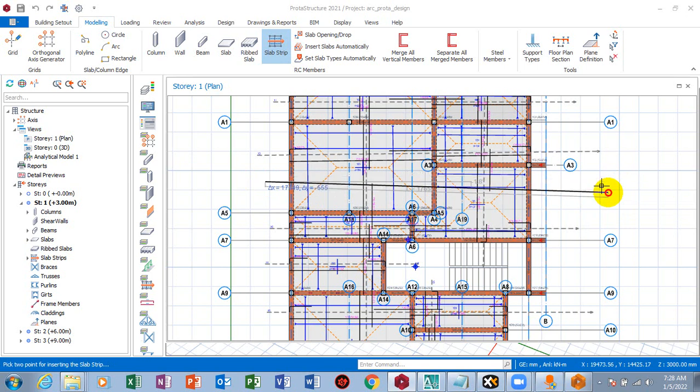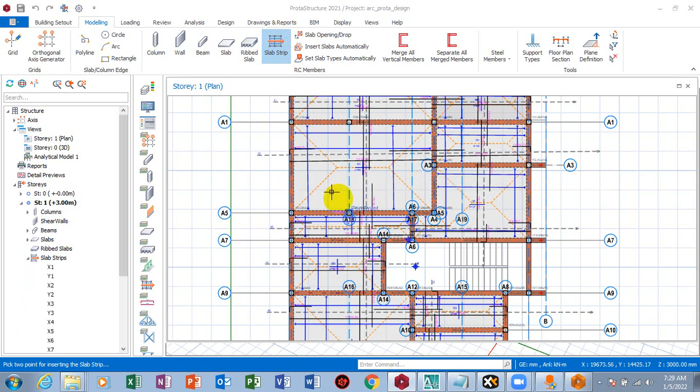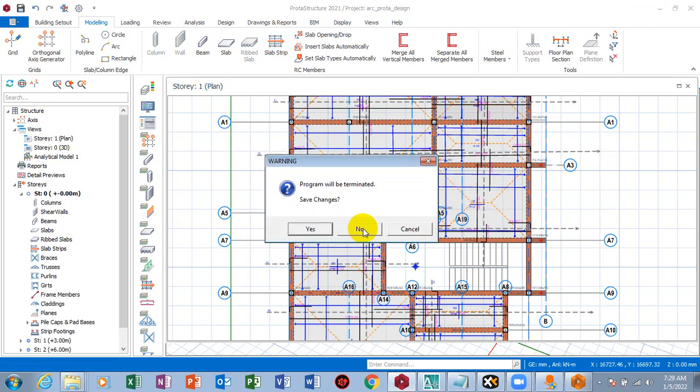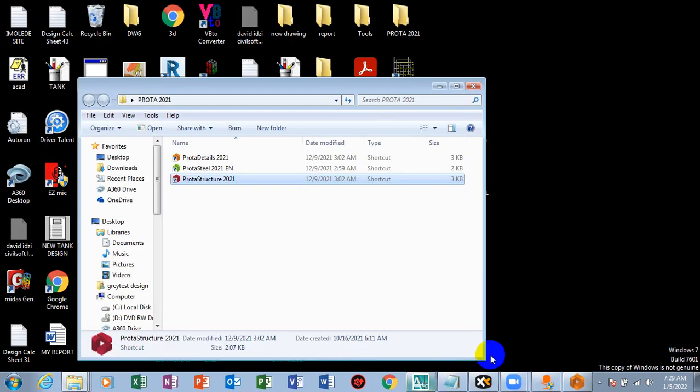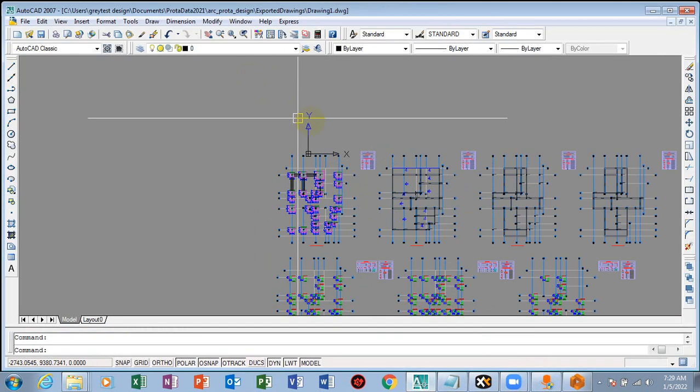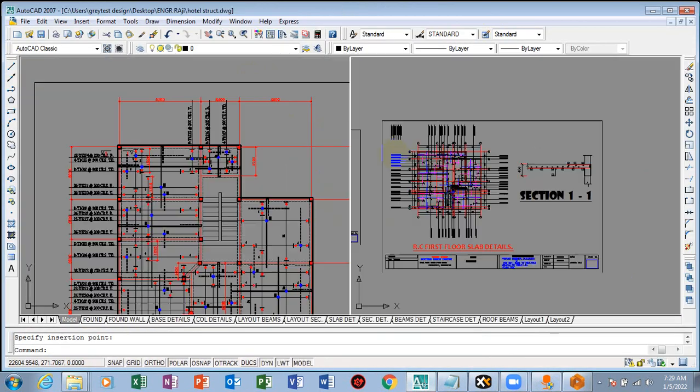I believe if you are familiar with AutoCAD, there's what they call polar tracking. So if you don't turn on your polar tracking, your lines may not be straight. Exactly, it's the same thing here. So I believe that's the reason why your lines are not straight. That is just an example of what I'm trying to talk about. So you can rerun that again in order for it to give you a better line.